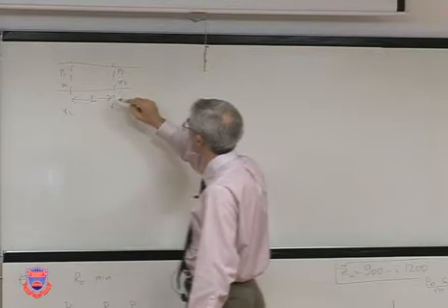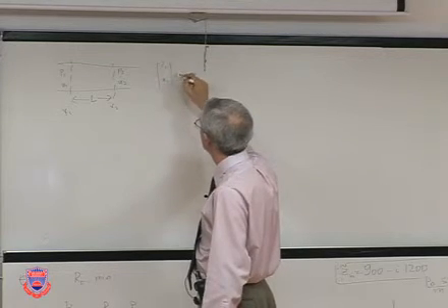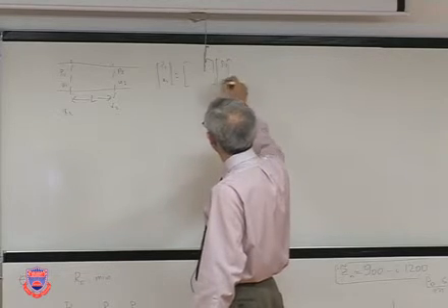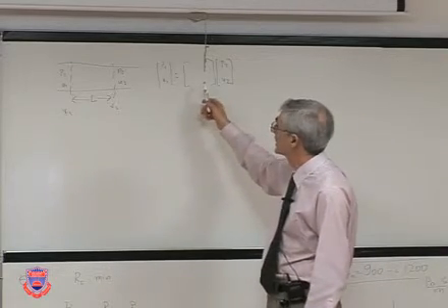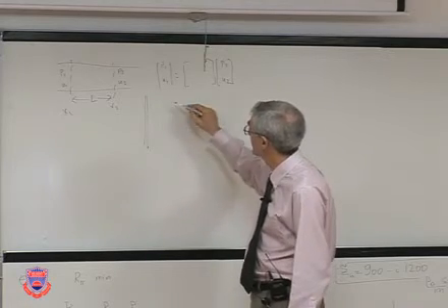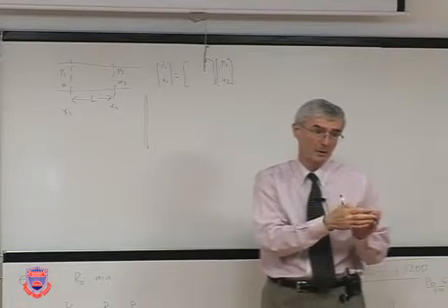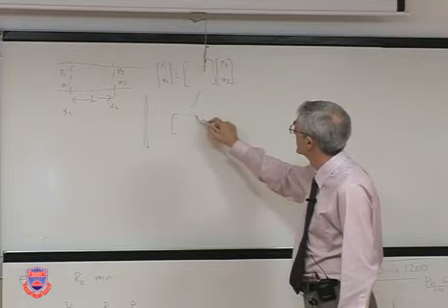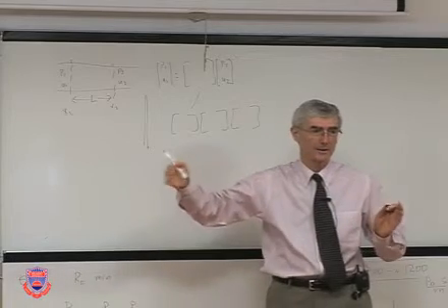The relationship between them is like a state equation, expressed as a matrix. You can develop these matrices for a silencer, for a membrane, for a plate, etc. To calculate the sound pressure, especially in a computer, all you have to do is put these matrices side by side, just the way they're organized.